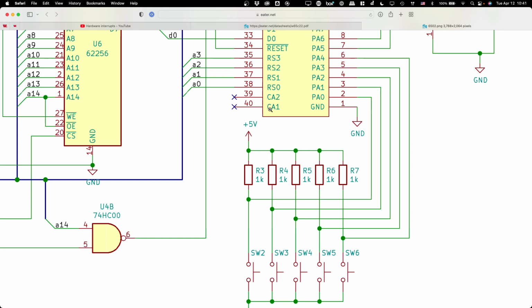OR and AND? Wouldn't you want an AND gate when all the inputs are tied to the same thing? Well, it depends on which way we do the logic. We could use either an OR gate or an AND gate, and the difference is basically just which way we think about the logic. Are we going to have the buttons pull low, which they do?